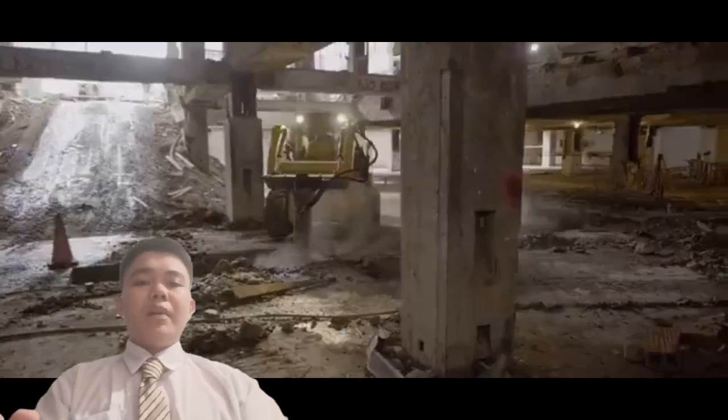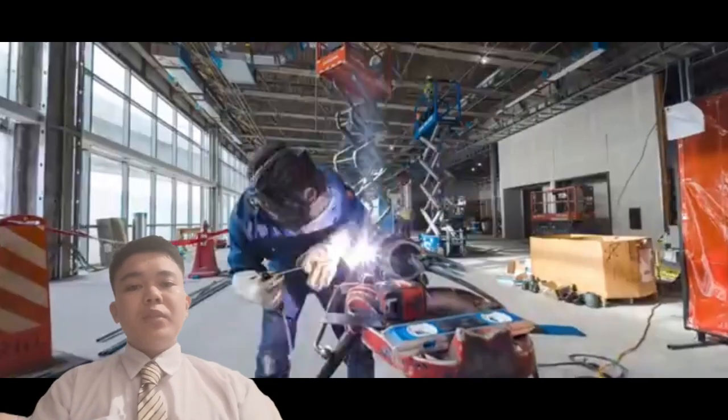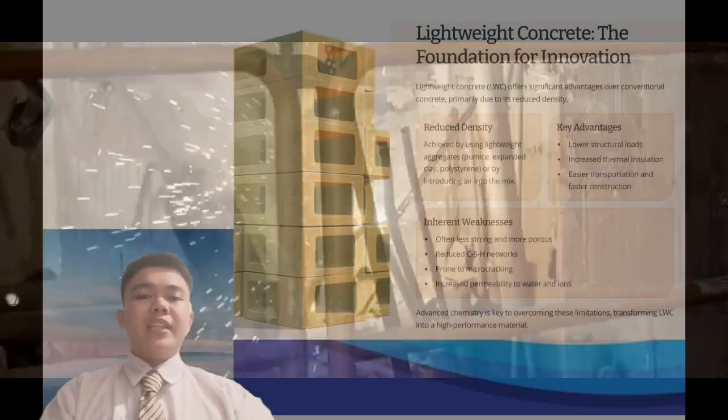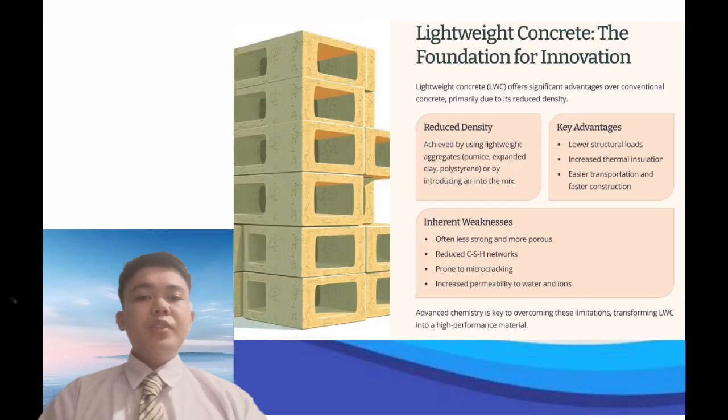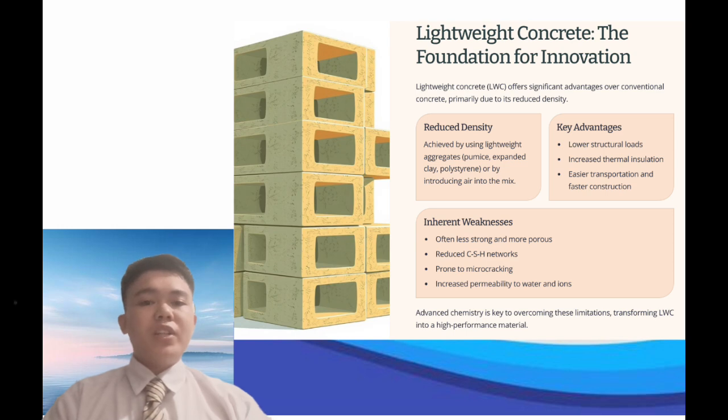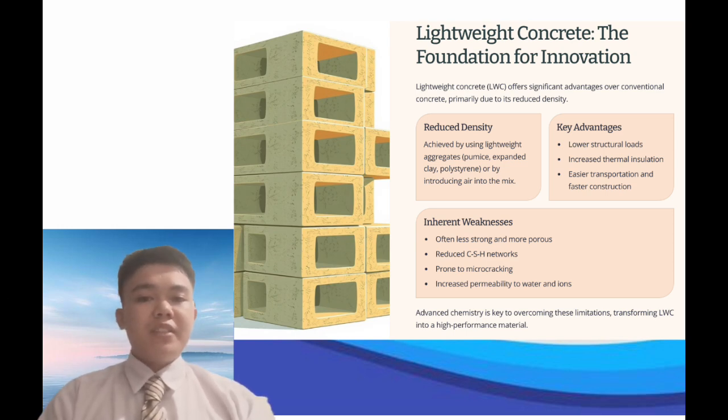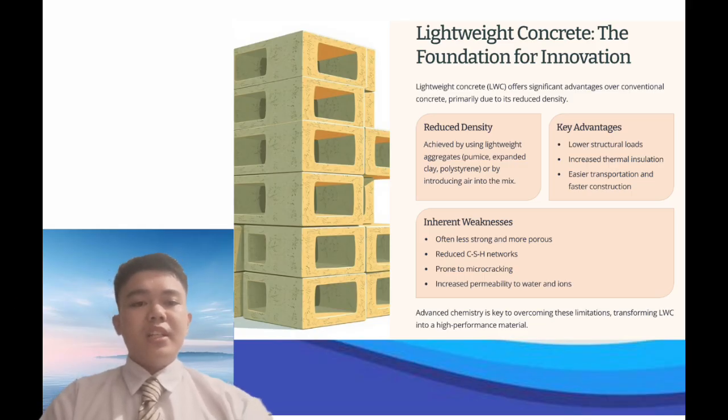So now let's talk about lightweight concrete. Lightweight concrete has a lower density than conventional concrete due to the use of lightweight aggregates, the introduction of air or aerated concrete, or the absence of the fine aggregates. It is utilized in floors, slabs, walls, and pre-stressed buildings and provides benefits such as lower structural loads, increased thermal insulation, and speedier construction.